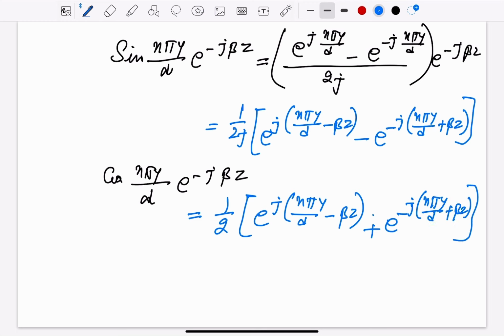So what we can conclude is that the wave in the parallel plate waveguide looks like the superposition of two plane waves, and it is being reflected between the two plates as the propagation happens. So one is this, another is this. You can see it like this because we assumed our solution in this manner.